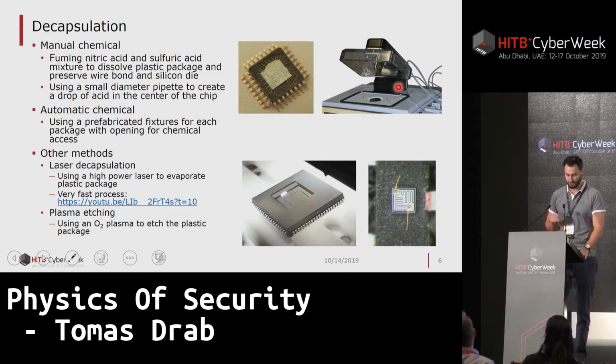Or you can go physically. You can use a laser to basically burn away the mold compound, and you will still have some residue of mold compound, so it's good to remove it using plasma etching. You basically use oxygen plasma to burn away the residual plastic.